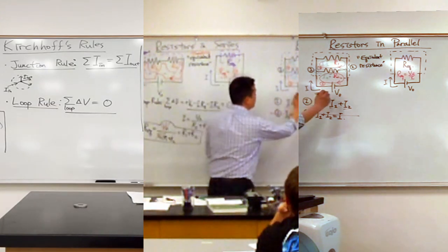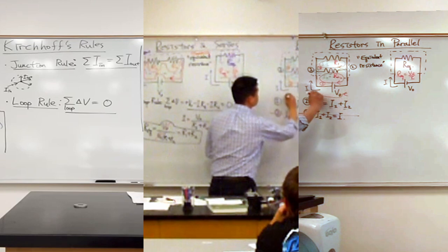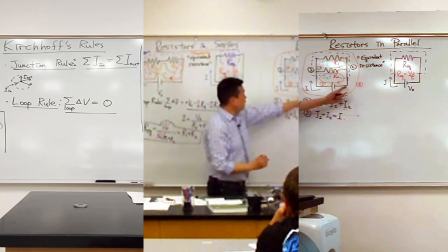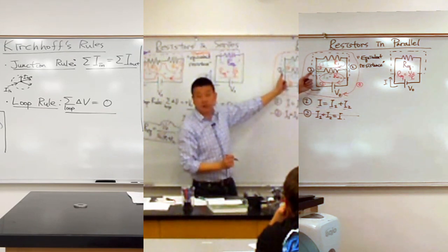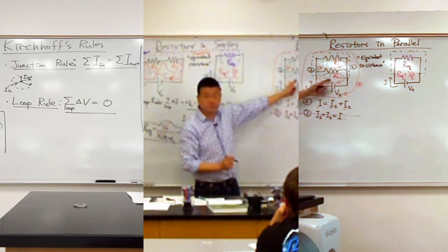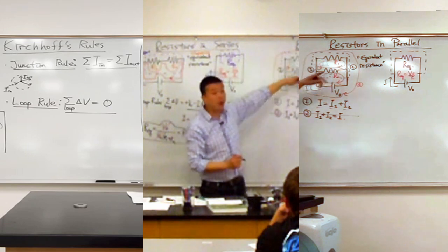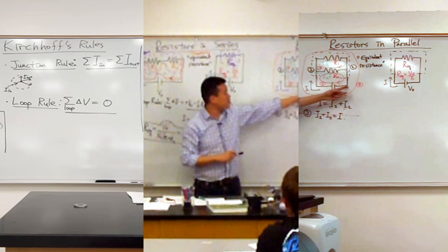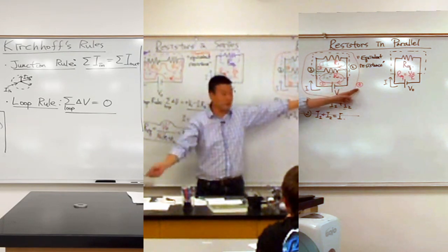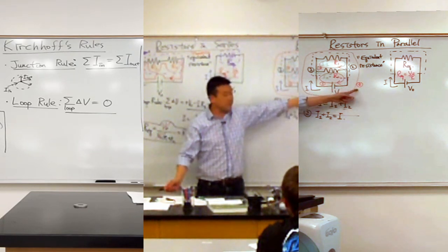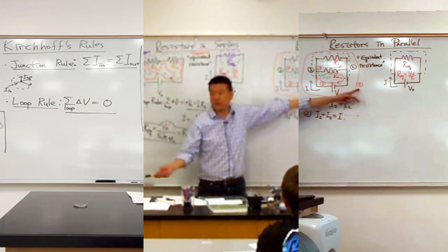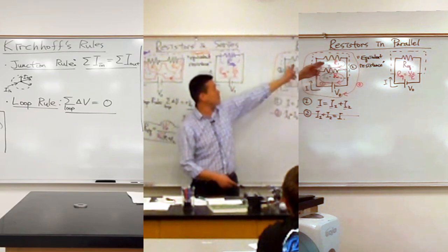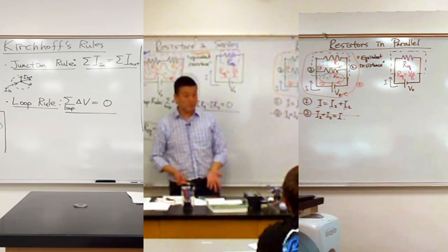Right? So, if I imagine going over this loop, say this is my third loop. For every part of the branch I'm going through, has it already been covered by the other loops? Yeah. So that's the sense. That's what I mean by overlap. And when the branch being covered by your loop has already been covered by another loop, then this is not going to give you any new equation, it's going to give you a dependent equation. So the advice I give to you is, define your loops in a way that minimizes overlap.